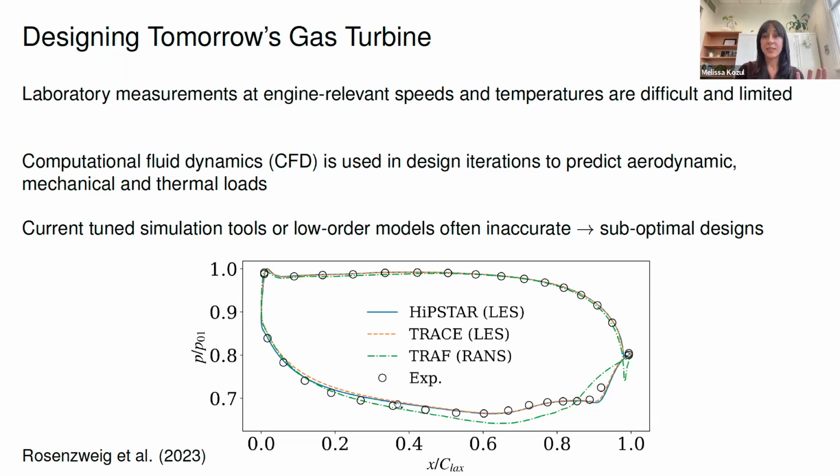And this actually is the top side of the blade, on this bottom side. And where it's mismatching, the flow is actually separating from the blade. It's mispredicting the separation of that flow from the blade, which is very bad. And this is an issue. We need to know this very precisely both to predict the efficiency, but even more practically, from the engine operator point of view, the actual reliability of this machine. And so this is quite a big error for this case.